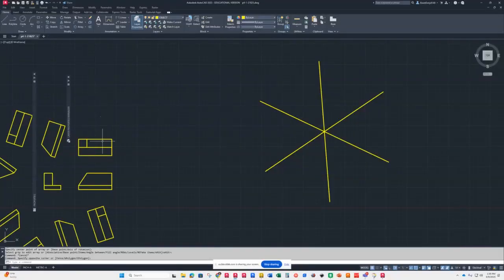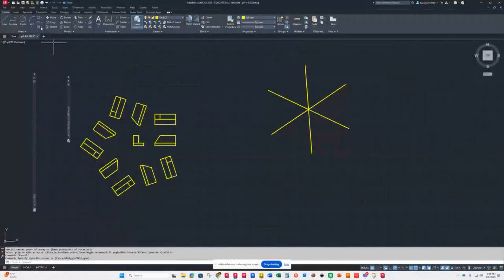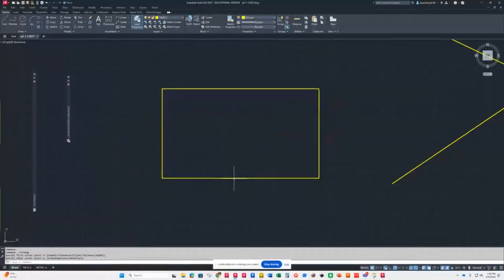So when you draw a rectangle, right? A rectangle is a polygon. It's all hooked together. Okay, well, what if you want to make another rectangle inside of that, a specific distance? I can do that. So let's say I wanted it on the outside of it. So I can use what we call the offset command. And then let's say I wanted it to come out this distance, whatever this distance is.